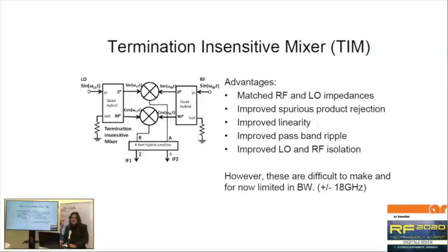Why? It's not that the VSWR is much better, although it is slightly, but it means that all the reflections coming from the nonlinear circuit of your mixer will be reflected back into the hybrid, and that hybrid will then reflect that into a termination. So that signal will not be reflected back into the inputs or the outputs. In this case, the surrounding circuit has the feeling that it will always transmit into a matched circuit. So that's a rather big advantage, especially if you're in communications.